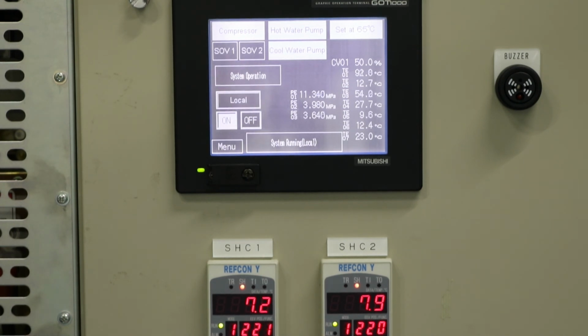The next pressure that you can see, the PE02, is the pressure at the section of the compressor, before the compressor. So the gas CO2 enters the compressor at the pressure 4 megapascal right now. And the temperature of it is 12.4. This is the temperature 02, PE02. The next set of temperatures are TE.3 and TE.04.